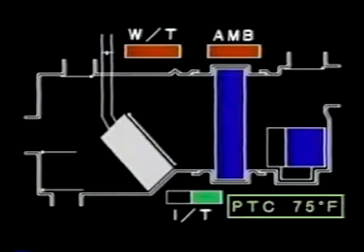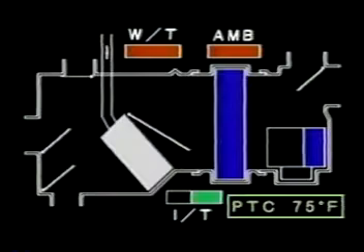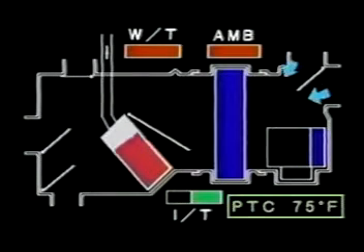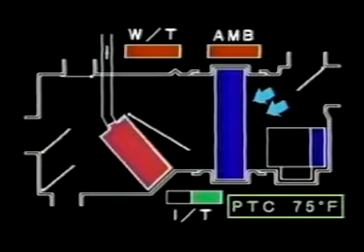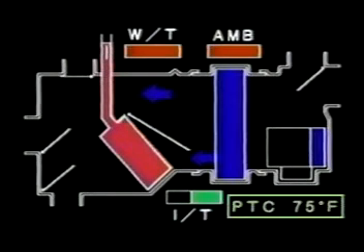As the in-vehicle temperature gradually approaches the set temperature, the air volume will gradually decrease. When the in-vehicle temperature reaches the set temperature, the amount of air volume will decrease to low volume. At last, with the in-vehicle temperature at the set temperature, the air intake position will change to a 20% fresh position. Depending on the outlet air temperature, the air outlet position may change to the bi-level position.